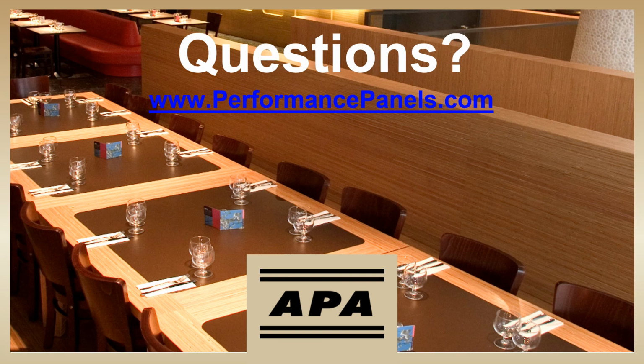Thanks, Warren. The next question that came in is, can OSB be used for concrete forming? That's an interesting question. So to start with, OSB is always an Exposure 1 bond classification. So as we covered earlier, this means that the panel should only be exposed to moisture during the normal construction process. These Exposure 1 panels are not meant to be exposed to repeated wetting and drying.